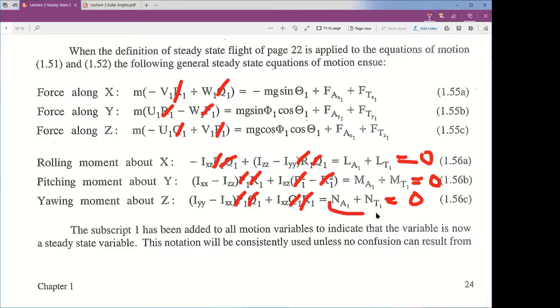The bottom equation, for the engine inoperative condition, is that we have a huge amount of yawing moment coming from our engine that's still operating out on the wing, and the other one's not. And so we have to generate an aerodynamic yawing moment from the rudder to keep the airplane from yawing, because we have to have the total yawing moment from the engine plus the rudder be 0. The problem with that is once we start doing that, we generate some sideslip, and the sideslip leads to some roll, so we're going to have to throw in some aileron to balance it all out as well. All right, so that's the steady state cruise flight condition.